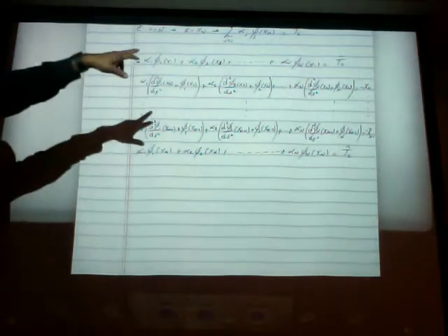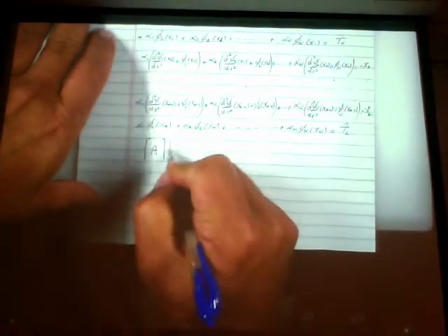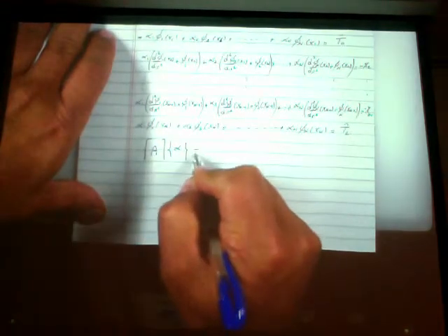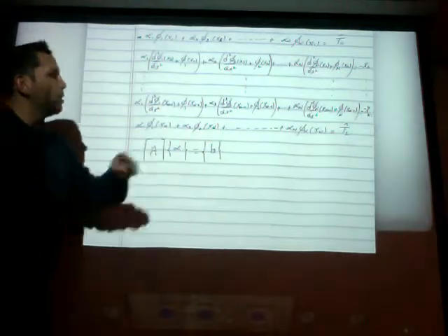So as you can see, you have n simultaneous equations for the n alphas that you're trying to find. And this seems like a fully populated system where all the coefficients exist in that matrix. So you have a matrix A times a vector alpha equals a right-hand side B, where that right-hand side B contains the T0, minus x2, minus x3, all the way to minus x n minus 1, and TL.